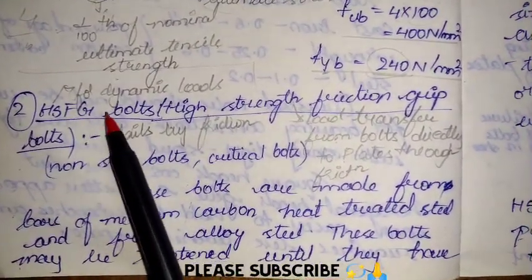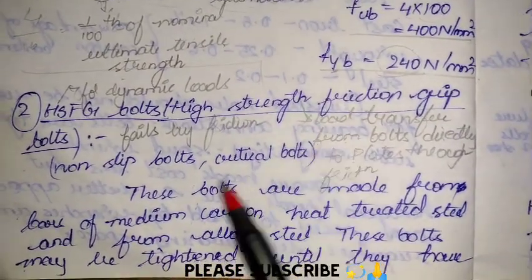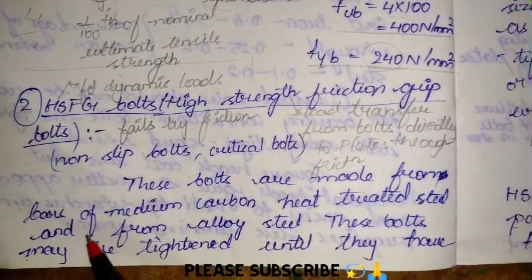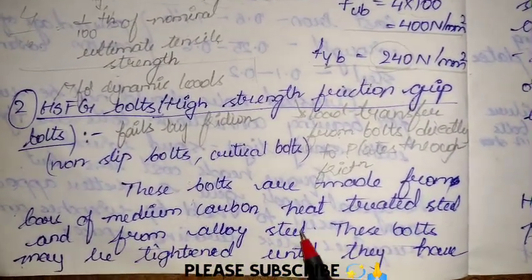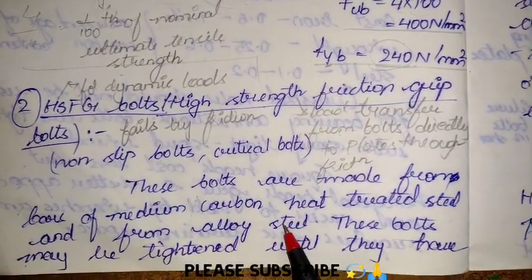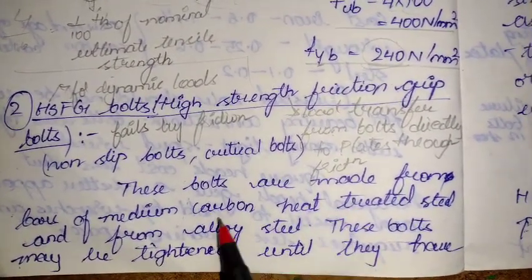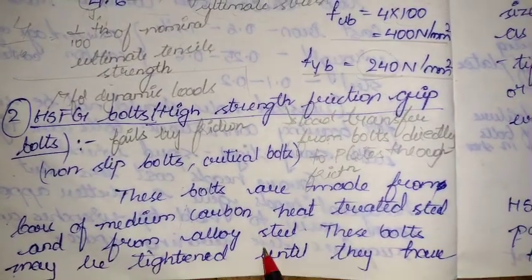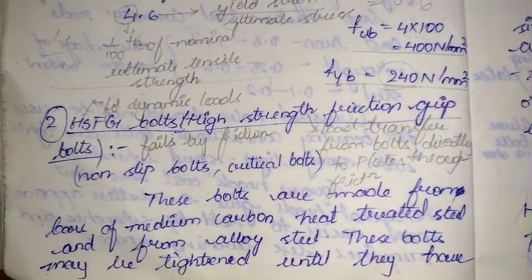So the HSFG bolts are non-slip bolts, critical bolts. These bolts are made from bars of medium carbon heat treated steel and from alloy steel. So we are using medium carbon heat treated steel and alloy steel, a combination of both, for these HSFG bolts.